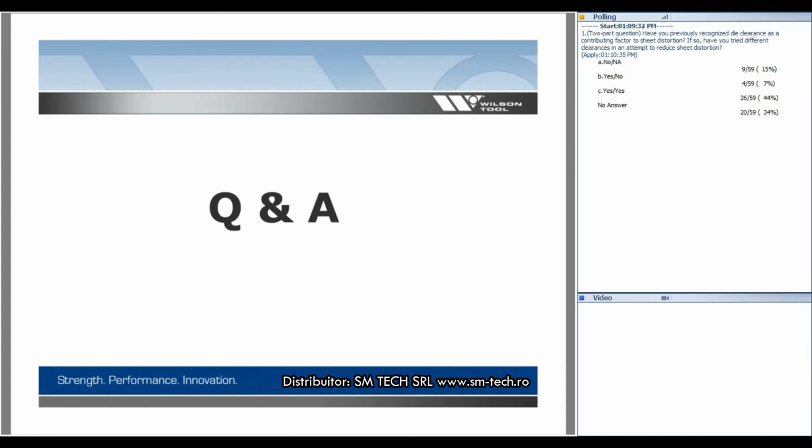I would mark the limitations as being, if you wanted a half-inch high rolled offset emboss, but you wanted that 45-degree sidewall, I can't produce a 45-degree sidewall. The reality is we're going to do a pinch factor and I'll get you your half-inch height, but it might end up being a 30-degree or 37-degree. We can't control it that minutely, so it's more of a prototyping process.